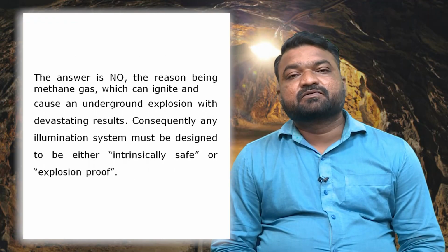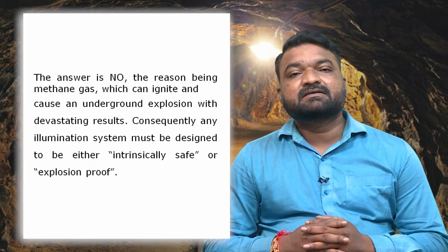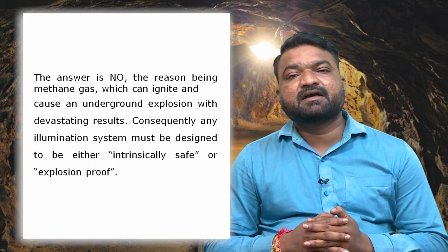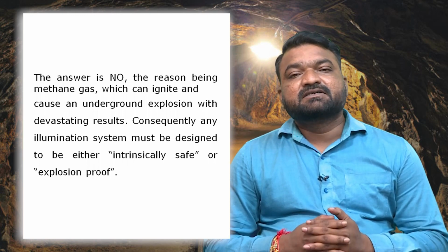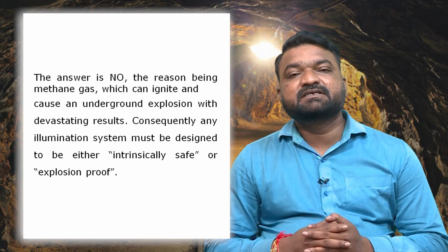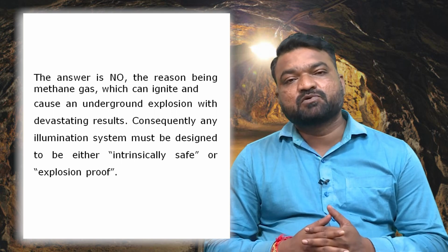The answer is no. The reason being methane gas, which can ignite and cause an underground explosion with devastating results. Consequently, any illumination system must be designed to be either intrinsically safe or explosion proof.